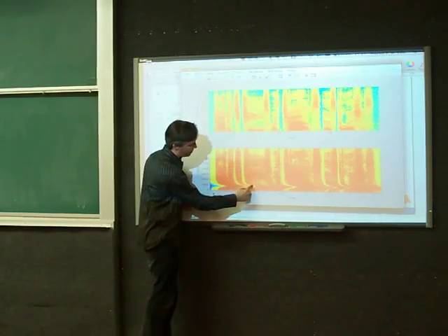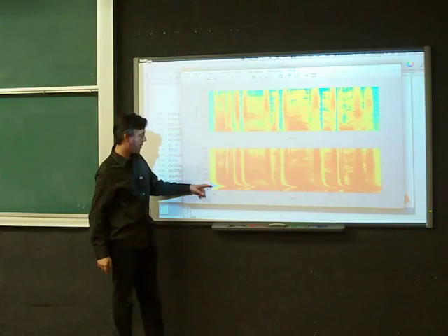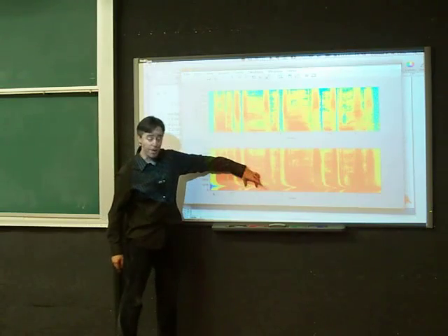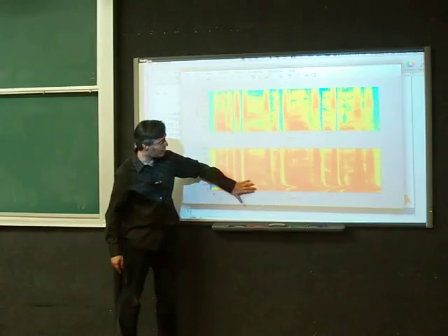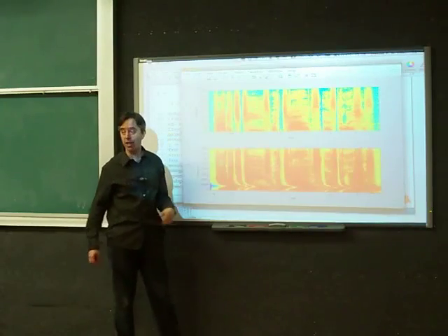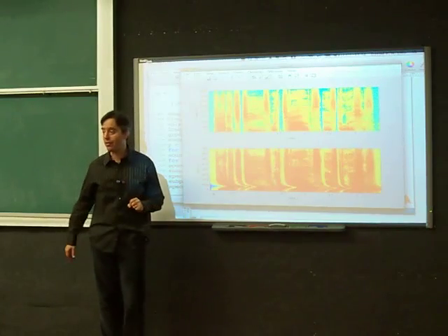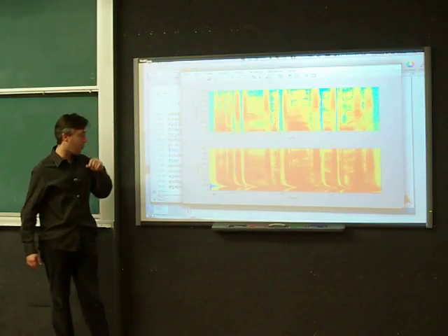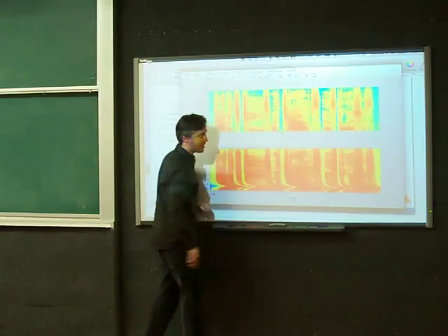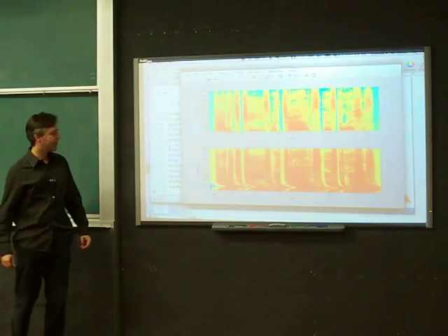And you can see that now in the region of this frequency, this peak in the group delay, which was 0.1 of the Nyquist rate, so at 800 hertz, we got a delay of about a quarter of a second. But it's just local to all the frequencies in this band. And this band here has been delayed a quarter of a second relative to the rest. And so everything's still there. It's just that it's been moved around in time in a non-uniform way. And what we hear is these squeaking sounds as these energy peaks move up in frequency. Yeah? It seems that we have more energy after we pass through.